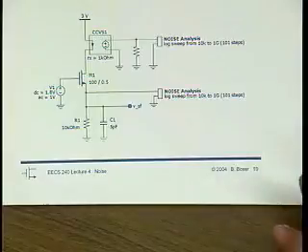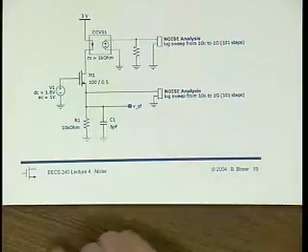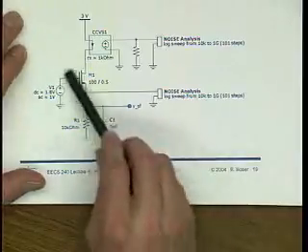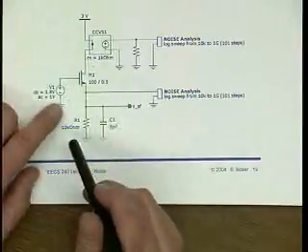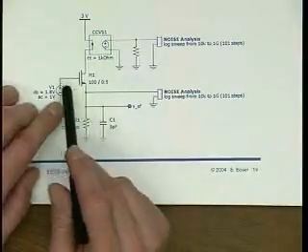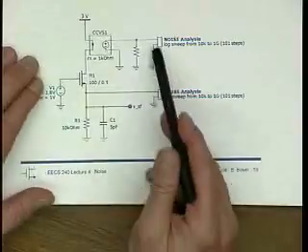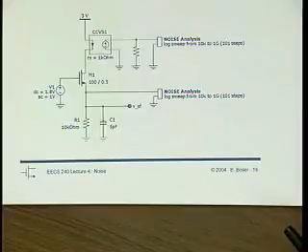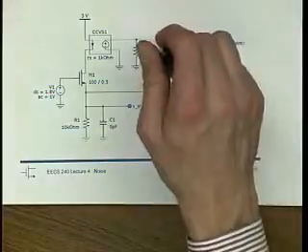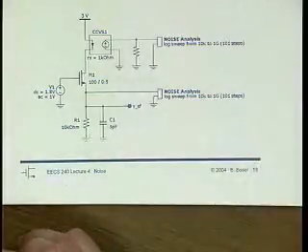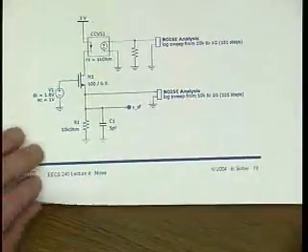Most of the time that's not a problem, because most circuits, an op-amp has one output, right? And it's pretty clear what that is. But sometimes a circuit can have more than one output, like here. This amplifier could be used as a degenerated common source amplifier or a source follower, right? And so we have these two different outputs. When we calculate the input-referred noise, we have to calculate the output noise either here or there, and then divide by the respective transfer function. The results are not going to be the same.